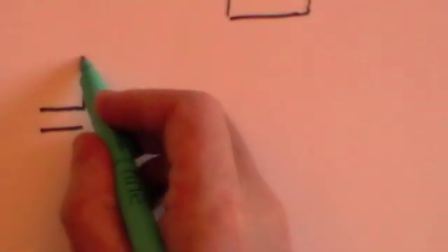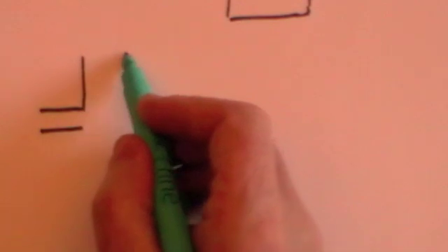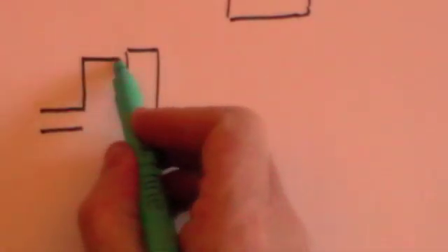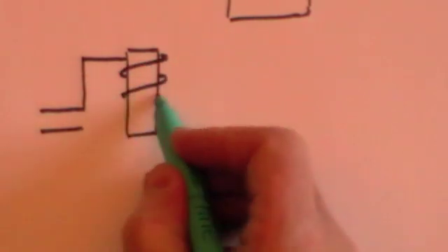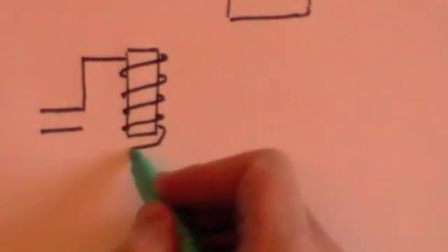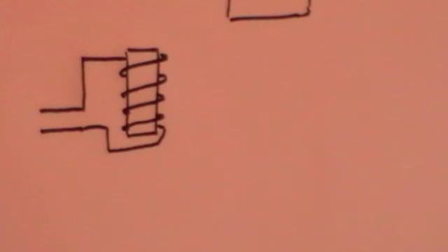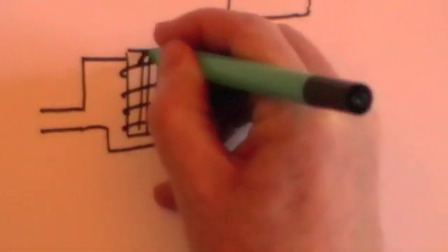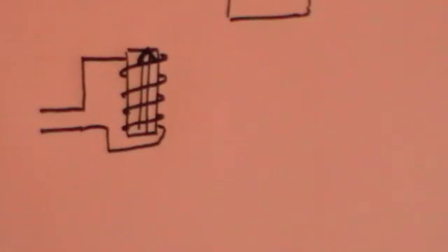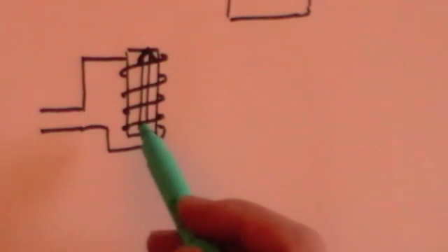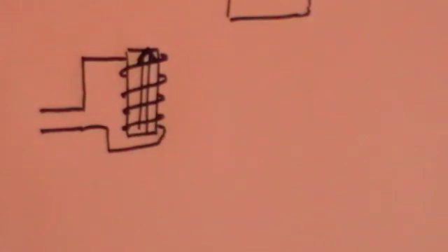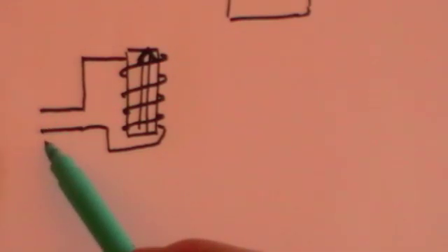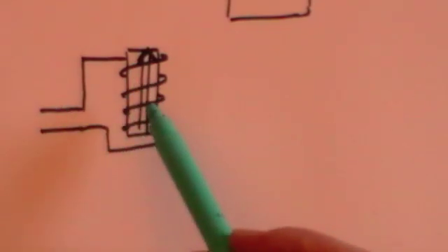So we're going to assume that there's going to be an output which is only positive if all of those warning signs materialise. And what you do with this output, instead of taking it to the light emitting diode as you did before, you actually take it to what's called a solenoid. Now we did do this when we did electromagnetism. A solenoid is just simply a sort of a bar of iron round which you wrap your coil of wire like this. And the idea is, of course, that when a current flows, this will create an electromagnet. So there'll be an electromagnet and a magnetic field created within the iron bar. But if there is no current in this circuit, then there will be no magnetic field. And so when all the conditions of your logic circuit are satisfied, a current flows and that turns this into a magnet.